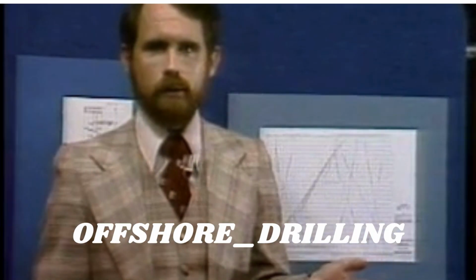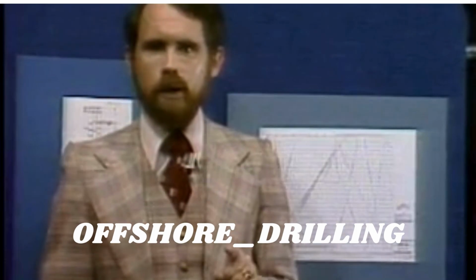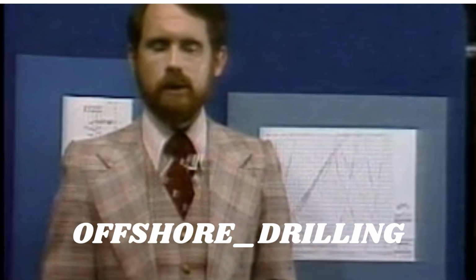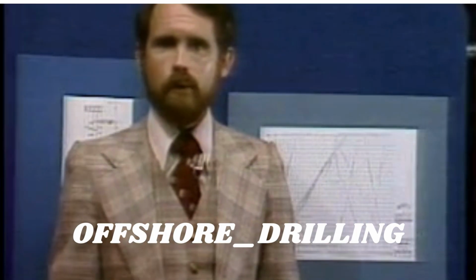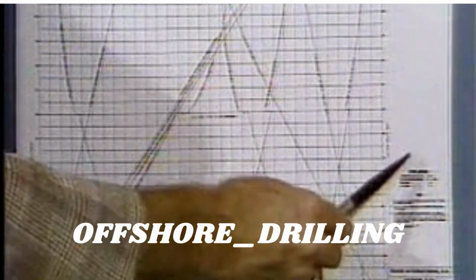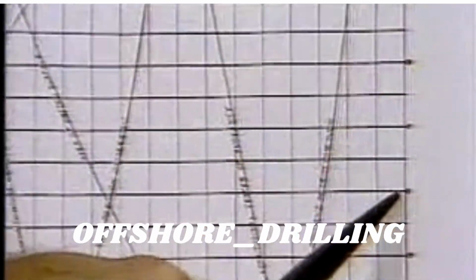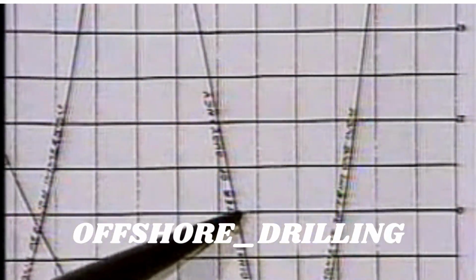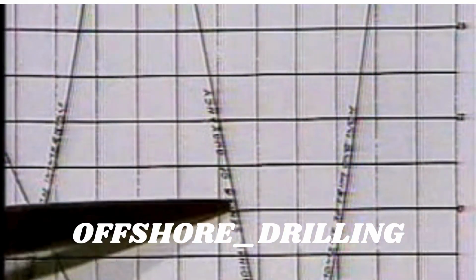draft reading. For example, if we want to locate the longitudinal center of buoyancy for a draft of 21 feet on the SEDCO 445, we find 21 feet on the right margin of the curves. Then we go along the 21-foot line until it crosses the longitudinal center of buoyancy curve.